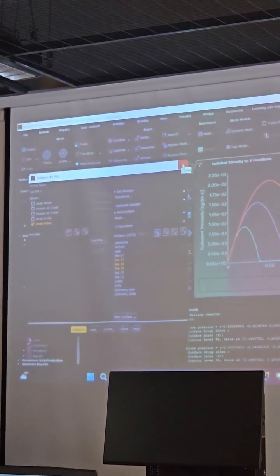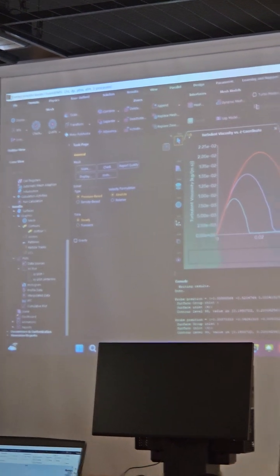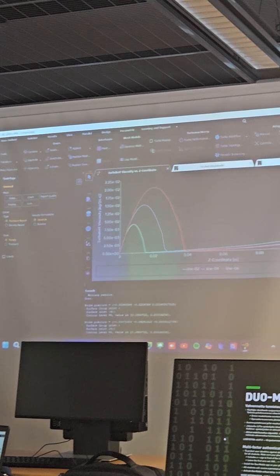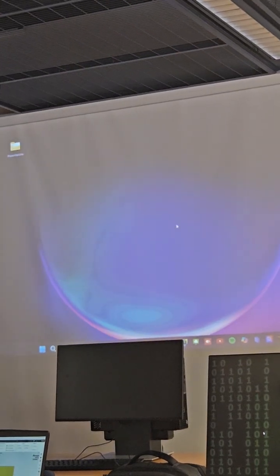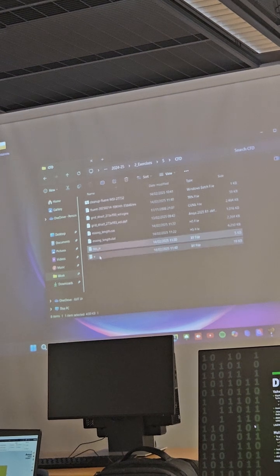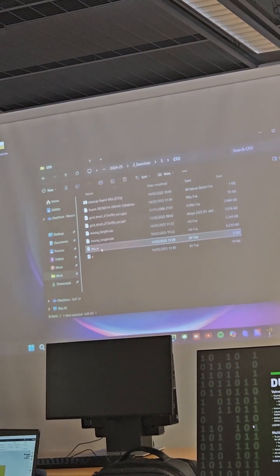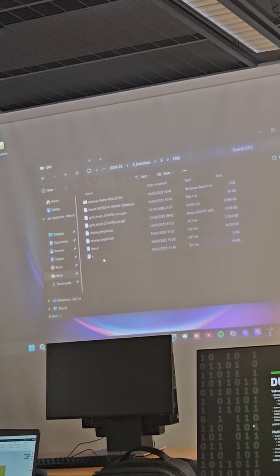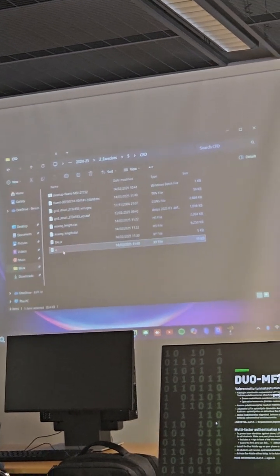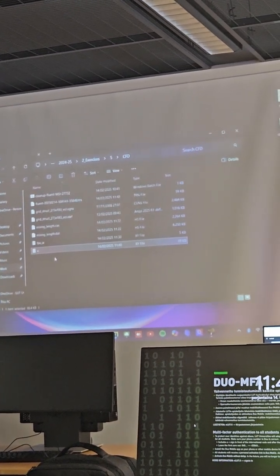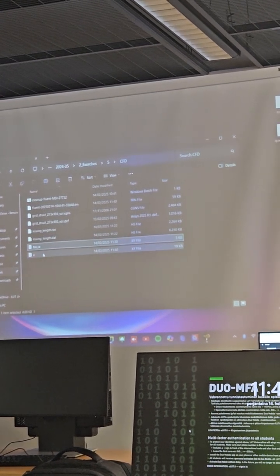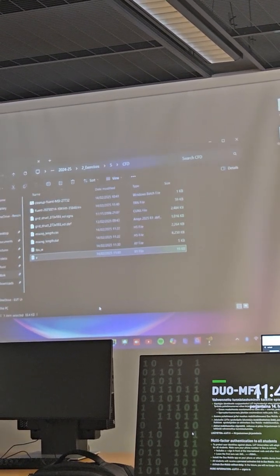Okay, now we have 20 minutes. I can try to show you how to post-process this data in Excel. So in your working folder, now you should have these two files, tau wall xy and v.xy, that have the distributions of wall shear stress and velocity. For those, the wall shear stress was calculated for the center line, and the velocities for the lines perpendicular to the plane.